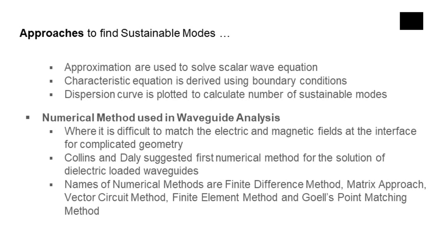In these numerical methods, a common feature is the formation of a matrix eigenvalue equation that is solved for the frequency, propagation constant, and the field in the waveguide. One of the first numerical methods was reported by Collins and Delhi for the solution of dielectric loaded waveguides. They used the finite difference method to discretize the Helmholtz equation for inhomogeneous waveguides.